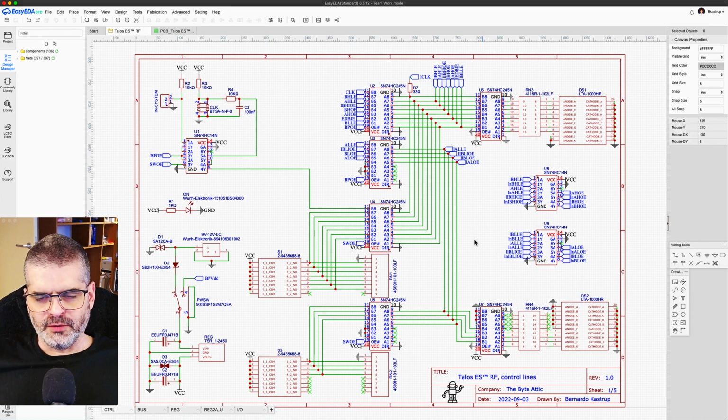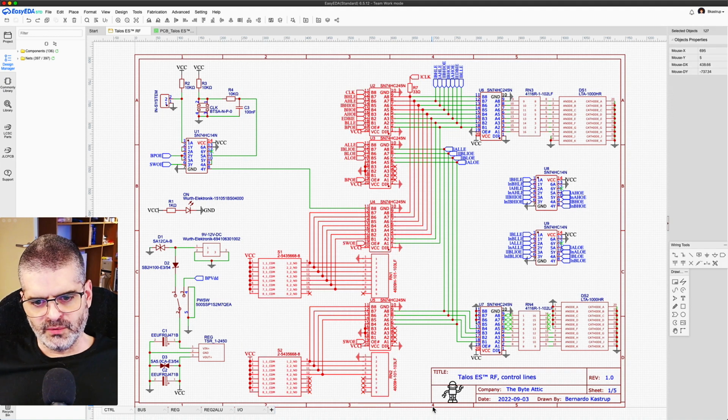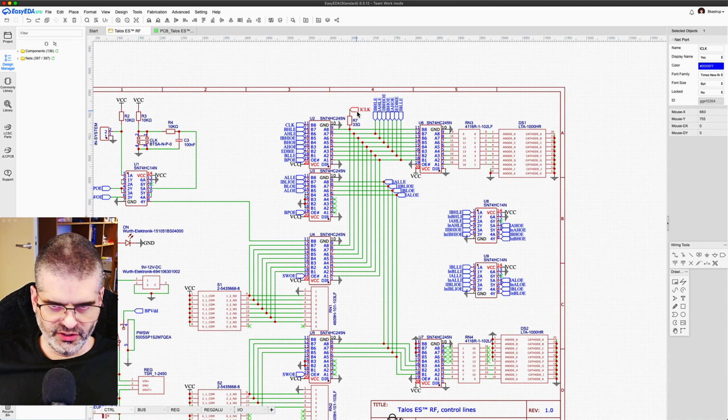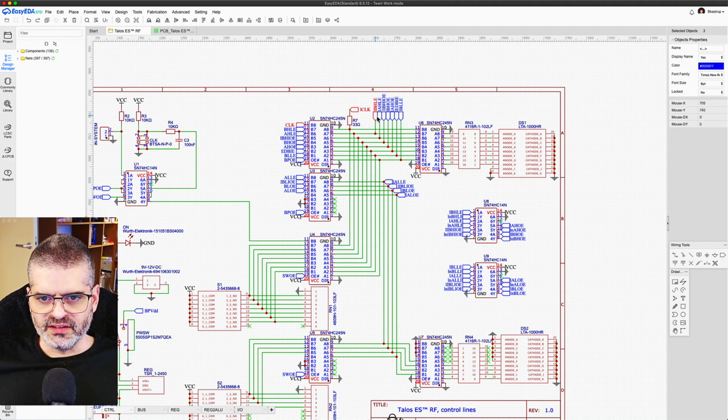This entire thing here decides whether the control signals come from the dip switches or the backplane connector. Once that choice was made, you get the same control signals, and the clock, on the other side, but now I add an L to their name to say local. Local means after selection. So this local B high load enable can either come from the backplane or from a dip switch. Either way, the result will be in this line here.